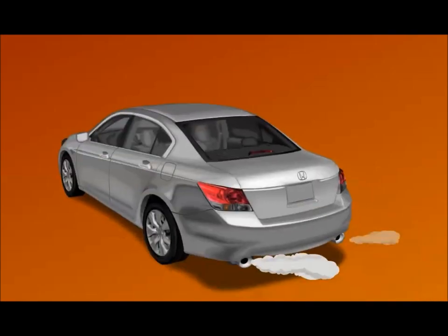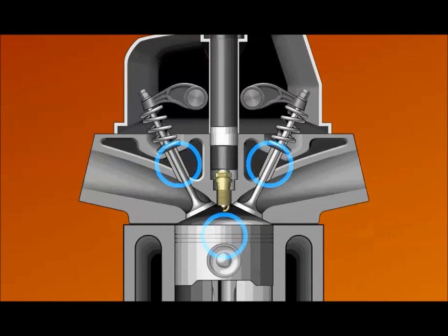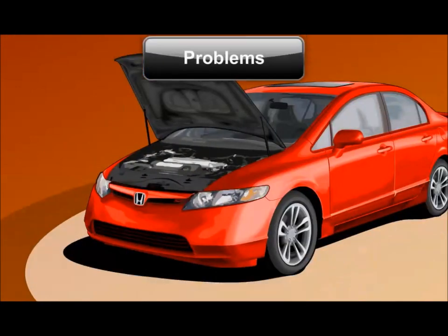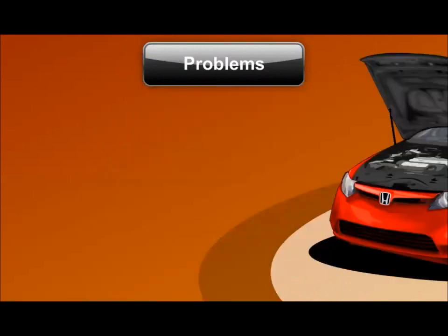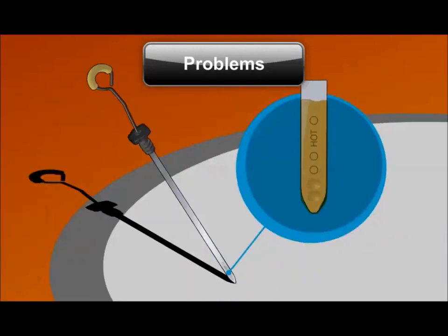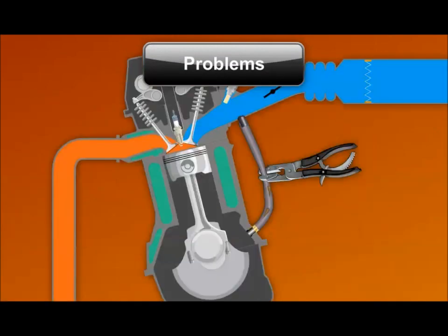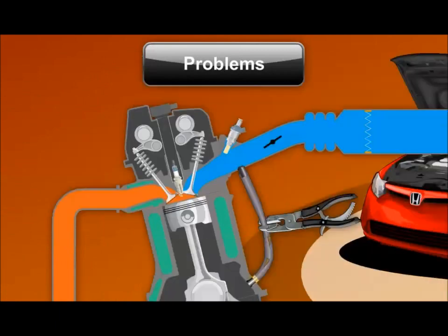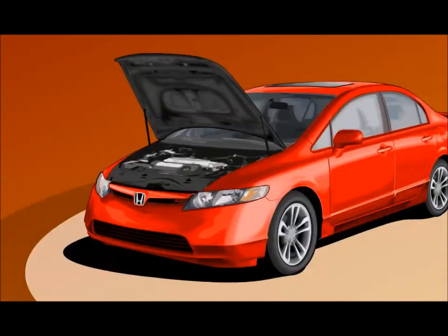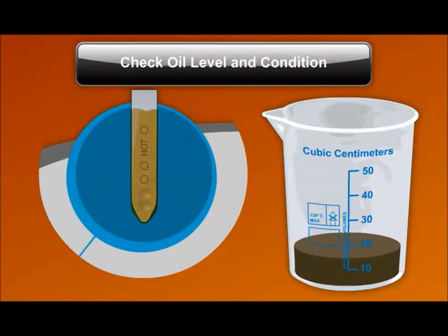When a vehicle produces white smoke at all times, the engine may have worn out internal components such as valve guides or piston rings. However, first check for problems such as poor oil quality, excessive oil fill, or a defective PCV system. This training module provides you with these basic checks in the Initial Checks section.